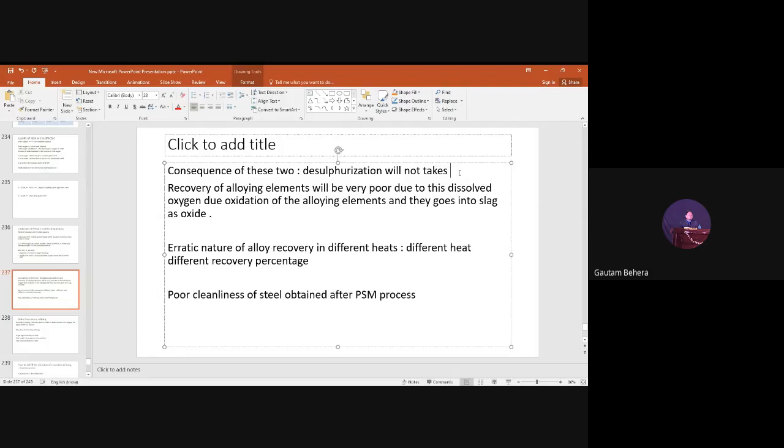So the oxidizing power of slag is determined by the weight percentage of FeO. Similarly, just the opposite, if the FeO weight percentage is less in the slag, it is a reducing slag. It also contains some amount of carbon, obviously. Right. So basically, to do desulfurization, we need a slag of reducing nature, or a slag with low FeO content. Right.